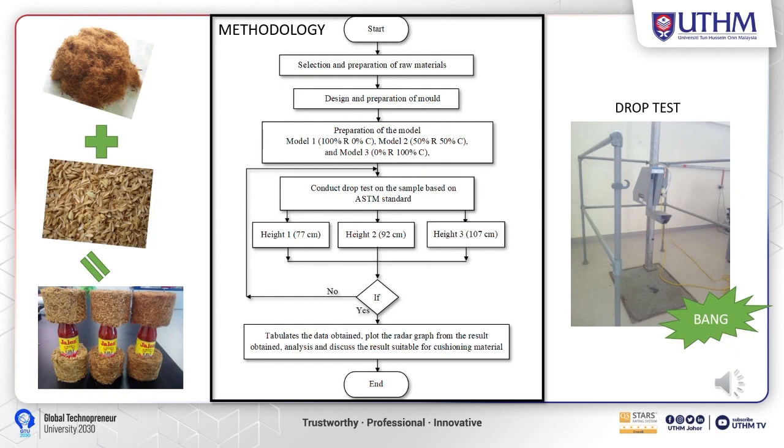After that, the ingredients are mixed perfectly and put into the mold that has been prepared. The mixture is then added in stages, where a 20 millimeter diameter PVC pipe is placed vertically in the center of a 102 millimeter diameter PVC pipe. The mixture was added progressively to fill the gap between the two PVC pipes until it reached a height of 35 millimeter. Pressure is then applied during the mixing to reduce entrapped air.